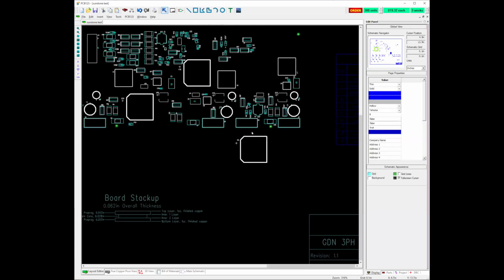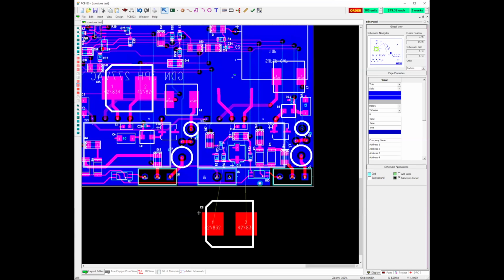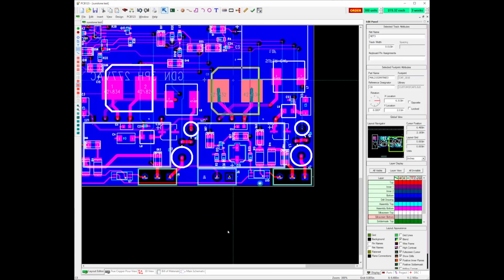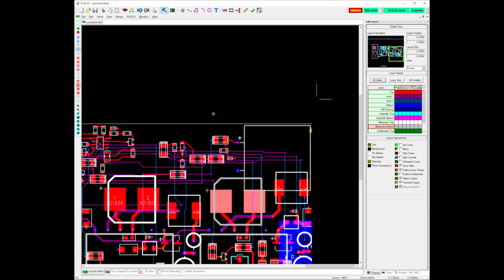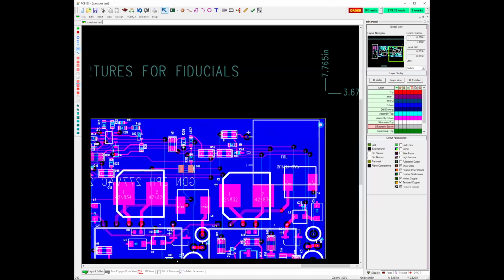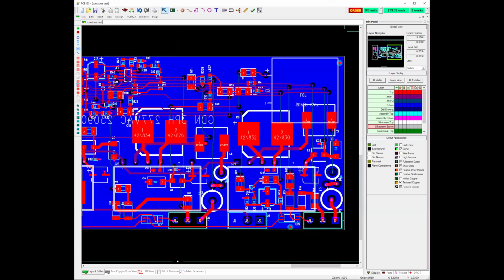Go to my layout editor. And all that's left to do is just take this part, plunk it down on those wires, and off we go. It's connected. I've got no errors, no guide wires, no disconnected anything. Everything's done. I've done this with some pretty big ICs that had a different, slightly smaller footprint, but the same pinout, that sort of thing. As much as 48 pins, and it works just the same. You don't lose all your routing.